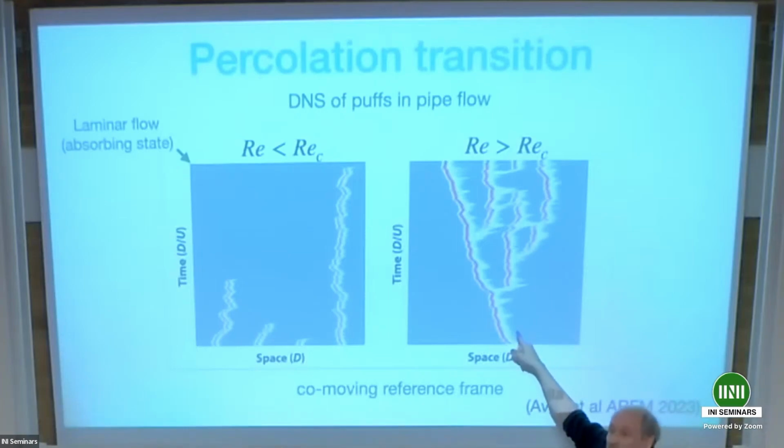And you see this phenomenon, it's referred to as splitting. It's a proliferation process. It's called puff splitting in the literature, so I'll just use that. Another puff, a daughter puff, comes off the parent puff, always on the downstream side in the case of pipe flow, and they proliferate like this.